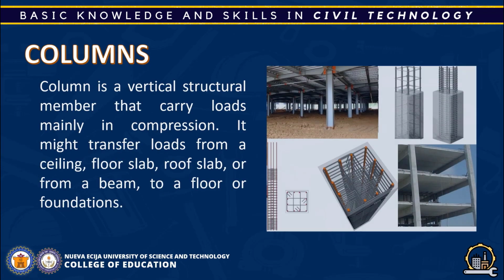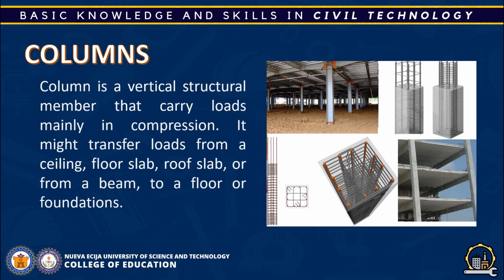Column is a vertical structural member that carries loads mainly in compression. It may transfer loads from ceiling, floor slab, roof slab, or from beam to a floor or foundations. The floor and the column on the floor above is supported by columns. The columns of the bottom floor must be large enough to bear the accumulative weight of each floor above it. They can move loads to the foundations and soil below from the slab and beams.